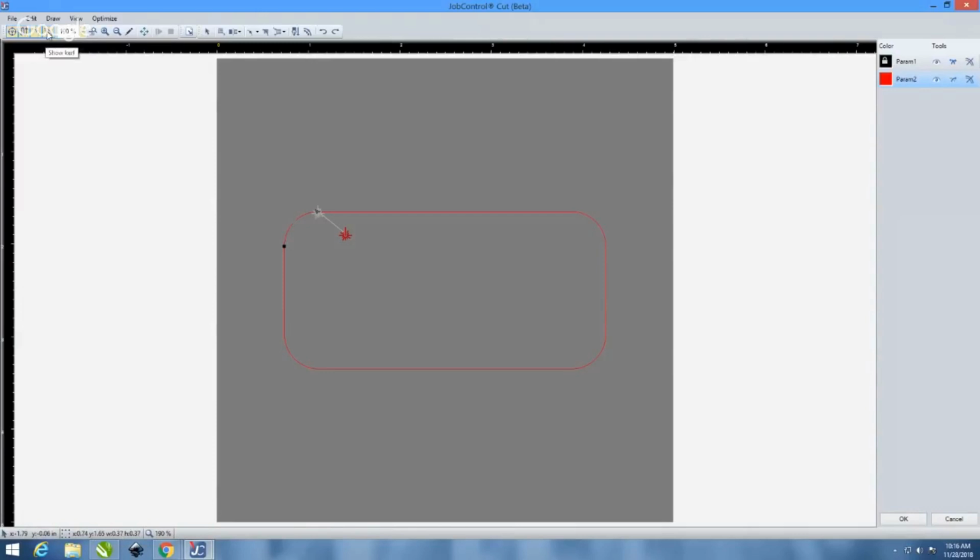Next, you can show, John, usually if you're cutting a piece of acrylic and the laser starts on the line, you have that tiny little blob. So you want to start it from coming in, right? Yeah. So Anthony, that's under draw, and you can do lead in there.